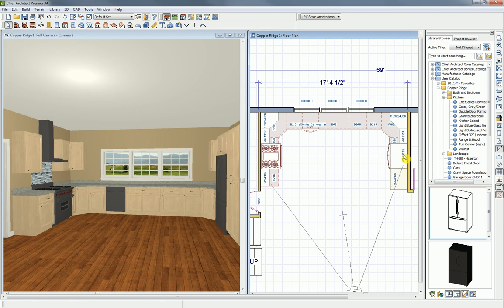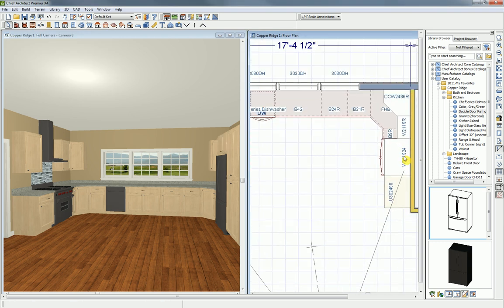And by the way, our cabinet labels are typical nomenclature for cabinets. So you'll notice that we have a full corner wall cabinet 24-36. So the dimensions are located. So when I snap that upper cabinet, I know that I've got my 24-inch by just briefly looking at the nomenclature. I'll just show you how that would be. That's 18. So you can notice how that's snapping in increments.